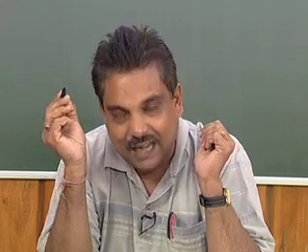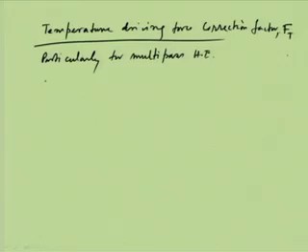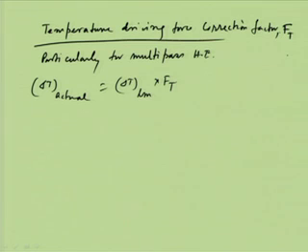and that is called the LMTD correction factor. So, we can say that delta T actual is delta T log mean into FT. FT is the correction factor, and as I said, it is for a multi-pass heat exchanger. This correction factor can be calculated from the figures, or it can be calculated from the expressions. For example, for a 1:2